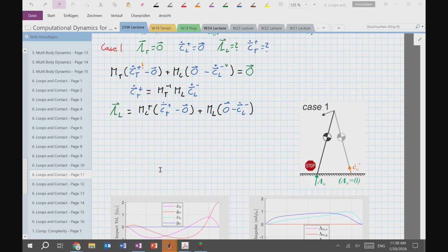And once you have that, then think about adding a hip joint. But maybe don't add a hip joint to a complex geometry where you have your femur head offset and weird geometries and initial conditions, but maybe just try that joint in the simplest configuration that you can think of and make sure that it behaves as expected, right?